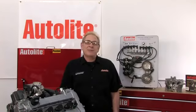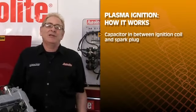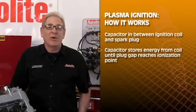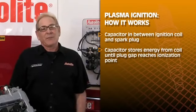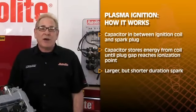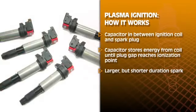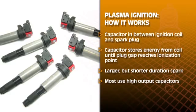The net energy output of a plasma spark can be much greater than a conventional spark. Let's look at how a plasma ignition works. Essentially, there's a capacitor in between the ignition coil and spark plug. The capacitor stores energy from the coil until the plug gap reaches its ionization point. Then, it will discharge with a larger but shorter duration spark. In fact, most current design plasma ignitions do not use a standard ignition coil. They use high output capacitors instead.